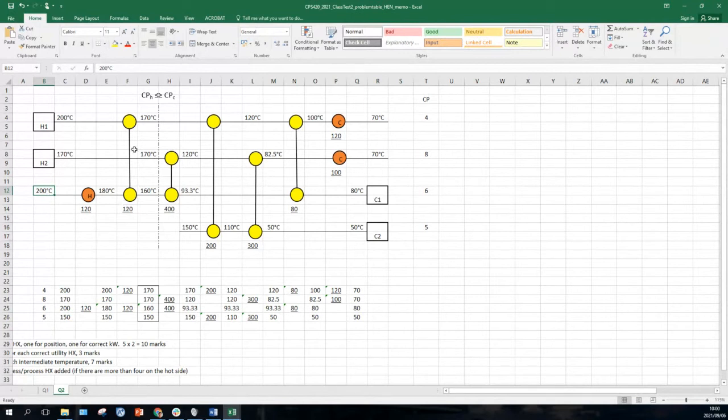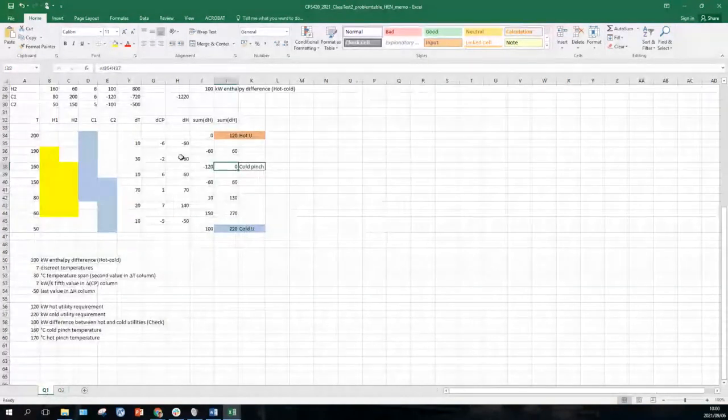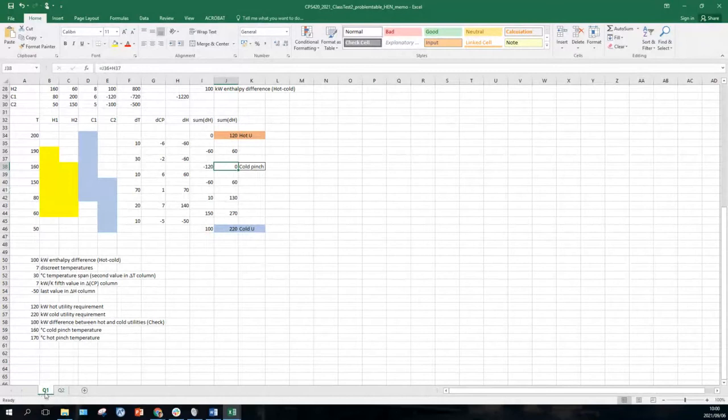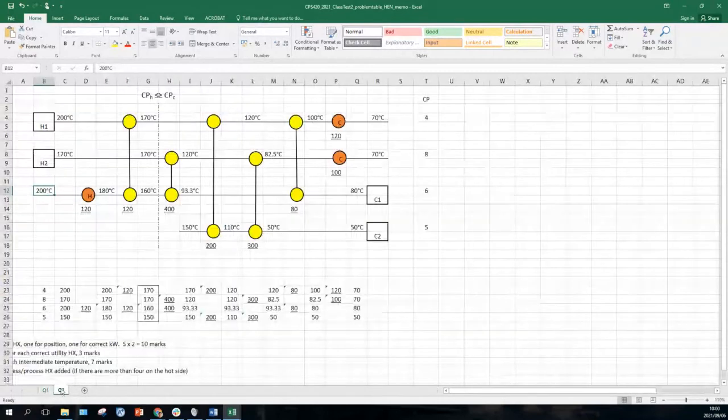And so we will use the smallest number. We don't want to subtract more than 120, otherwise we're transferring heat across the pinch. So that's 120. And then, of course, to make up the 240 required to heat up the stream, we'll use our steam, which is 120. And yes, it is the same as the MER that we've got on the previous page. Let's quickly go to the previous page, and there it was, 120. Okay.